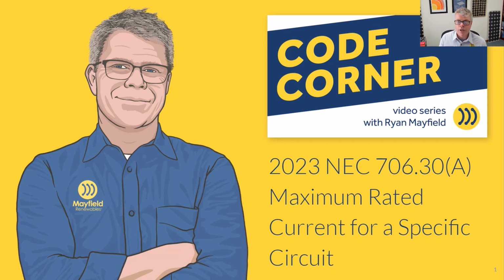For those of you that have been working in the solar industry and have been using Article 690 for a while, this really is similar to what we do in 690.8, where we are sizing the circuit currents for the different parts of the PV system. So that's kind of a correlation. You've been doing similar things before, and for our energy storage systems, this is where we're going to look to help define what those maximum circuit currents are.